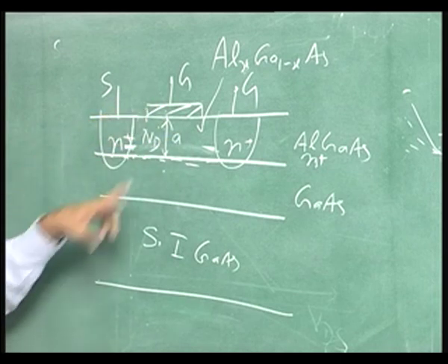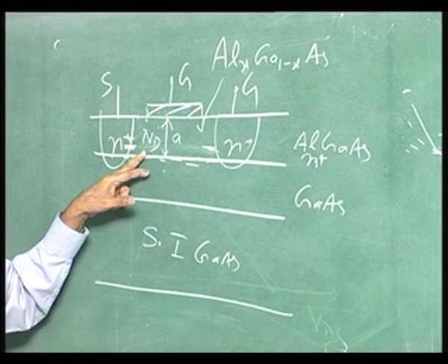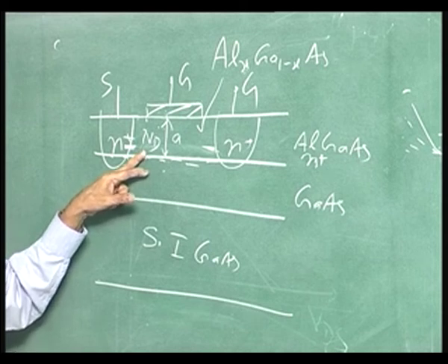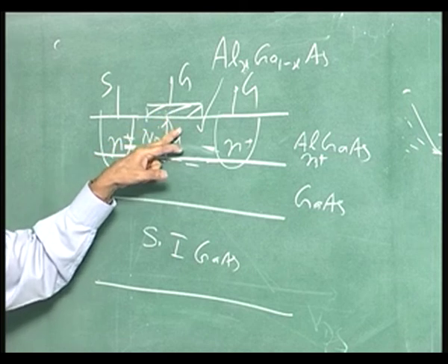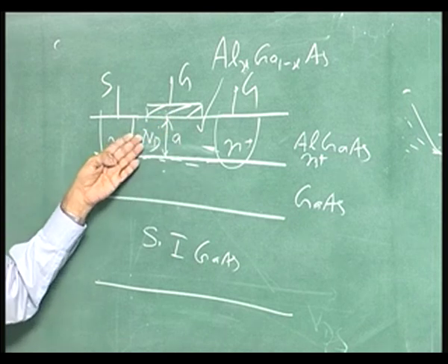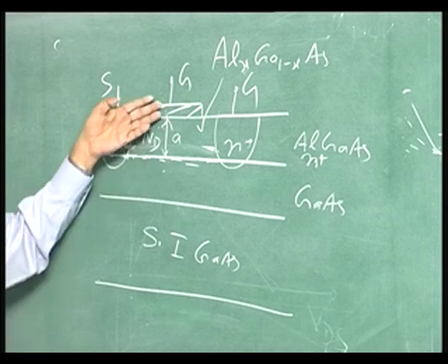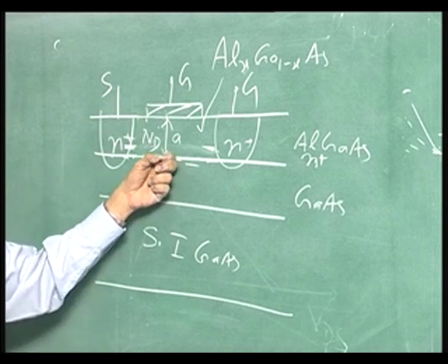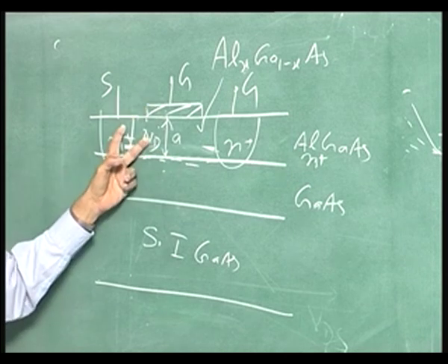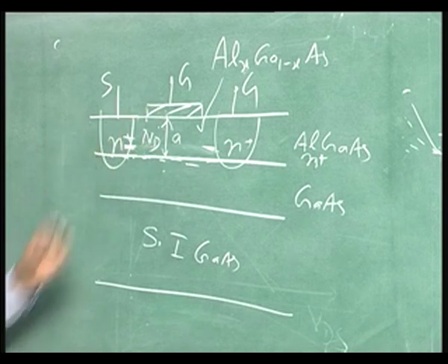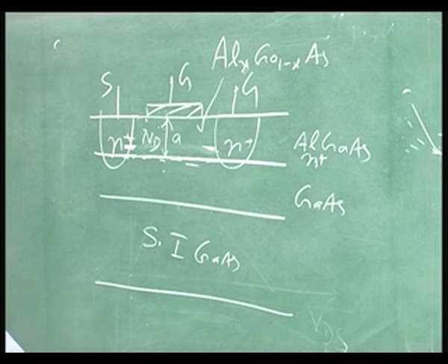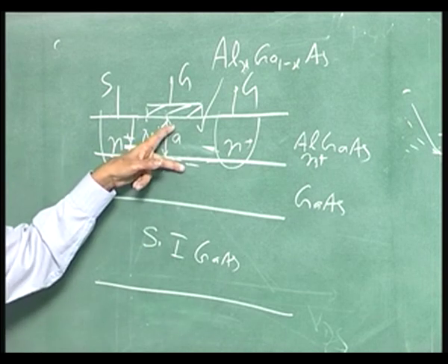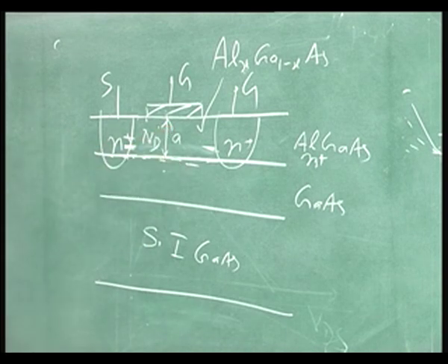Okay. Now, doping, there is an upper limit, because the Schottky will start conducting. So, the maximum doping is about 10 to the power 18. Correspondingly, you can go down to lower A for a given threshold voltage. So, there is a lower limit on A and an upper limit on ND. Upper limit 10 to the power 18. Now, depending upon your threshold voltage, you choose this A. You can't go beyond that for ND.